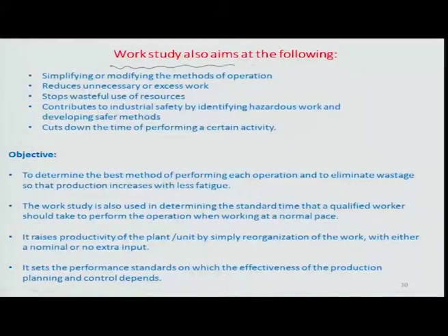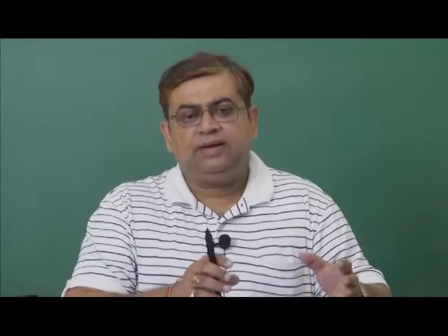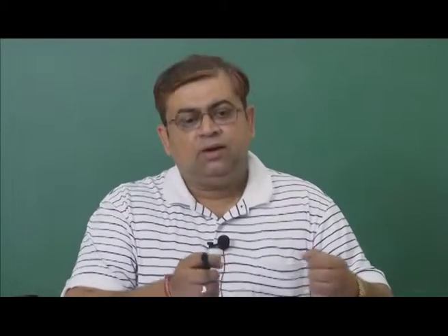So, there are several other aims that work study also addresses, and some of them are that it simplifies or modifies the existing method of operations. I had mentioned in great detail yesterday how just by making the system a little more automatic, by making a carriage which carries a coolant gun along with a vehicle, when we are filling the coolant in the final assembly line of a product, you could actually avoid the unsafe practice where the operator does the job of filling himself while moving forward.